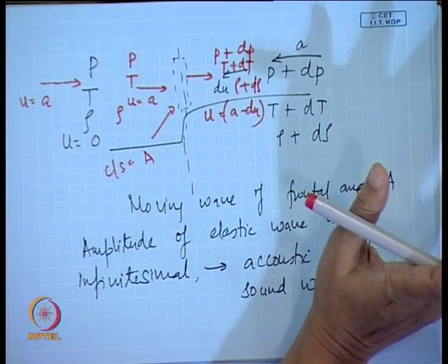Did you understand this portion? Just for performing the mass balance and the momentum balance, we want a particular control volume. So, we enclose that infinitesimal area by which the pressure pulse is enclosed, and that small area is actually travelling. We superimpose another velocity from the opposite side, so that the small area becomes stationary, and then we can assume that fluid is entering that area from the left hand side and going out from the right hand side.